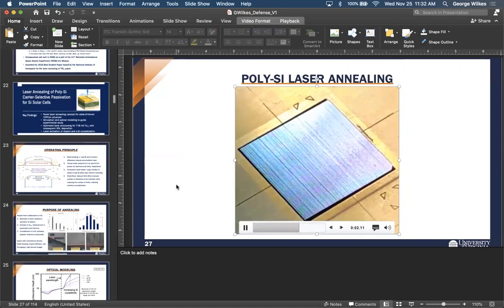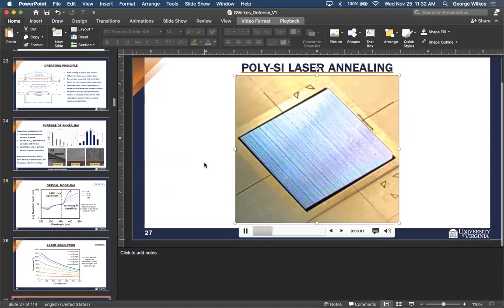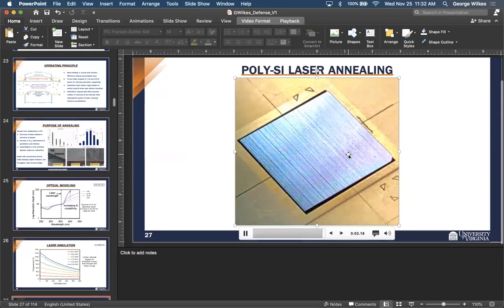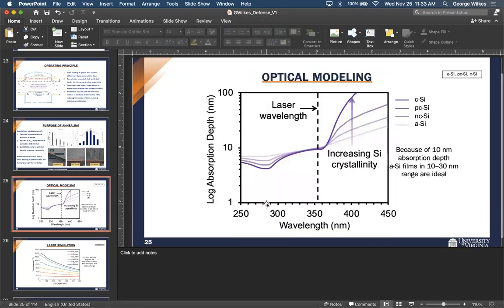So this is silicon, right? Yeah, this is polysilicon that's shifting in color. So what makes those colors shift? Is it the surface morphology or the intrinsic n and k property of the polycrystalline silicon? I believe it's an n and k property, so the refractive index will increase substantially with the crystallization. The n is pretty low at first, and then I think the n peak is somewhere in that 300 to 400 nanometer range. This is the absorption depth, but n is also.